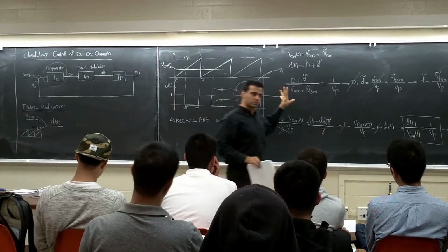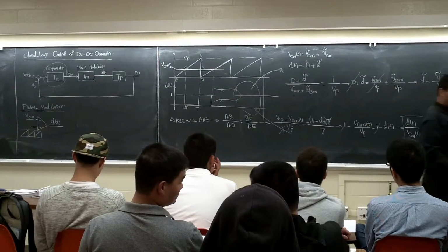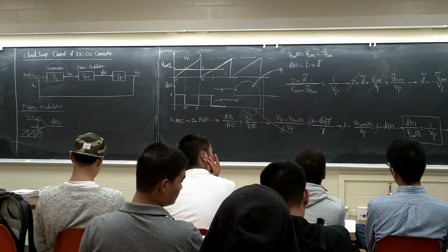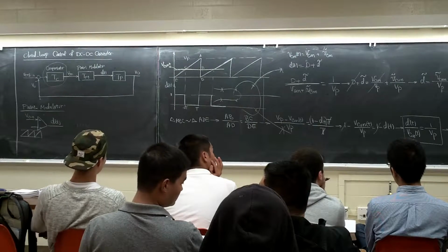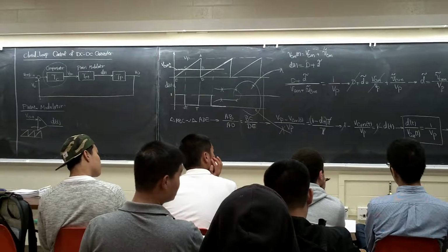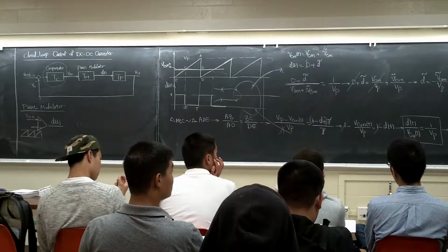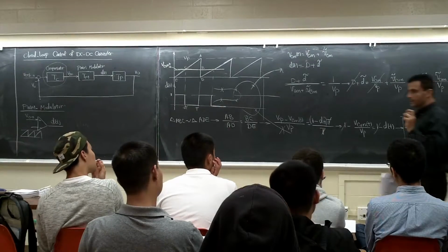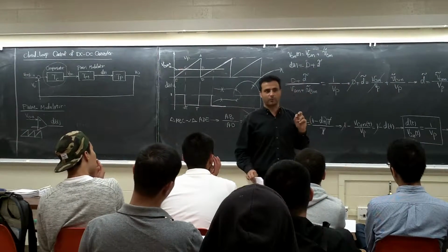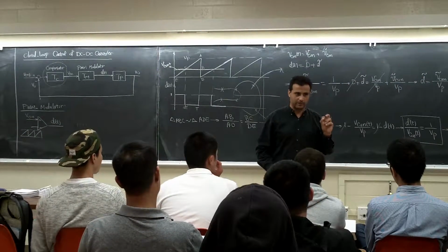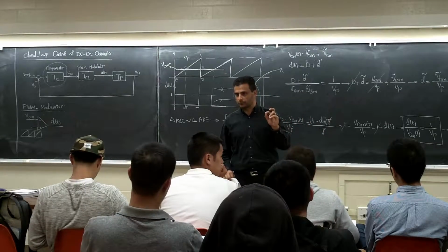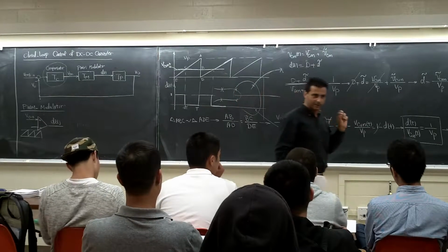I don't want to go into the detail of control theory. We are not going to talk about the root locus. But for part 3 of the project, you design the system for critical damping. Don't forget that one, critical damping. You can start with a time constant of 1 millisecond. That's a pretty good number. Use that one for your control, the KP you have, 1 millisecond.